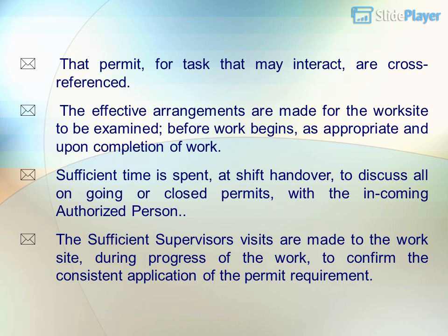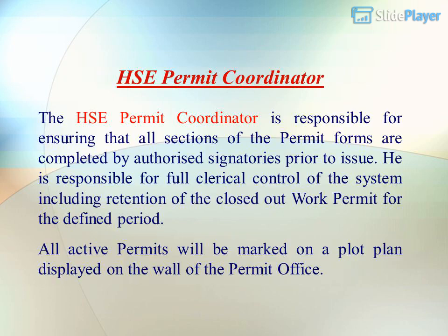Effective arrangements are made for the worksite to be examined before work begins, as appropriate, and upon completion of work. Sufficient time is spent, at shift handover, to discuss all ongoing or closed permits with the incoming authorized person. Sufficient supervisor visits are made to the work site, during progress of the work, to confirm the consistent application of the permit requirements. HSE Permit Coordinator.